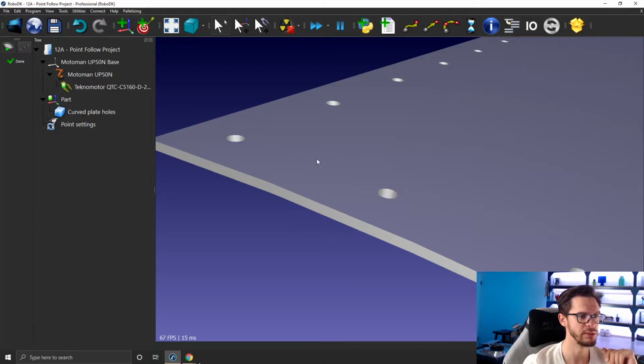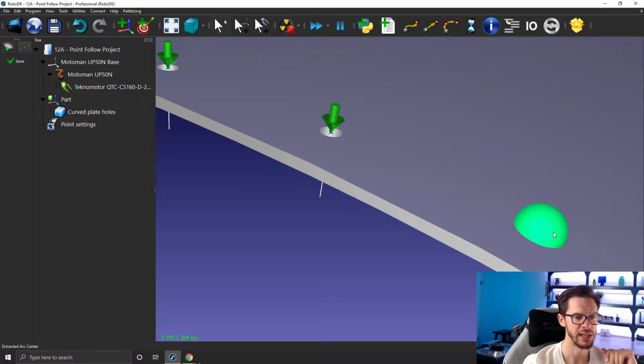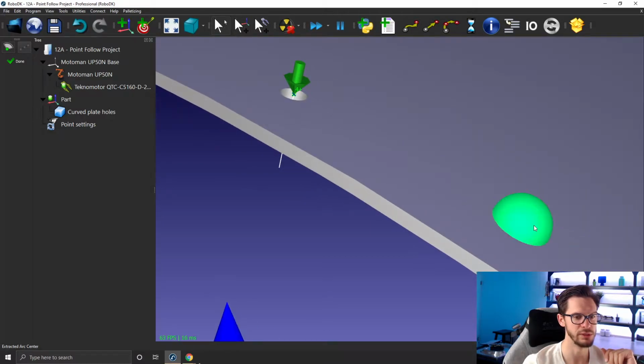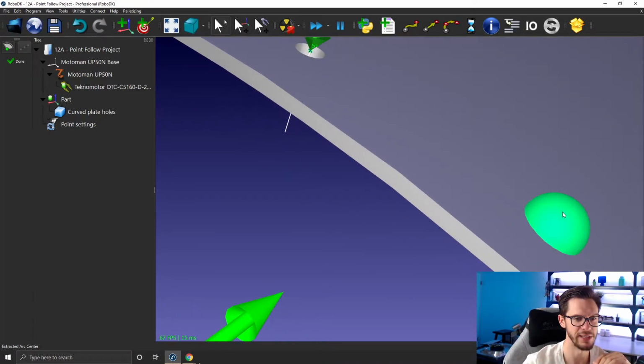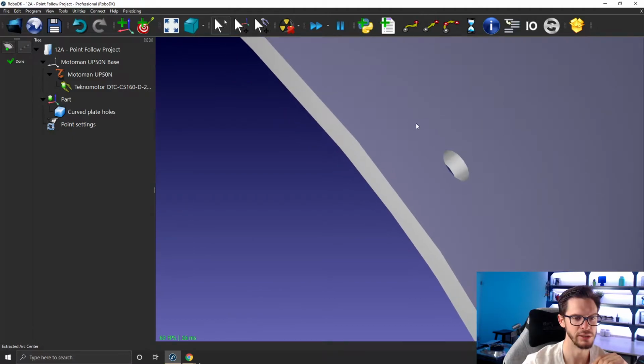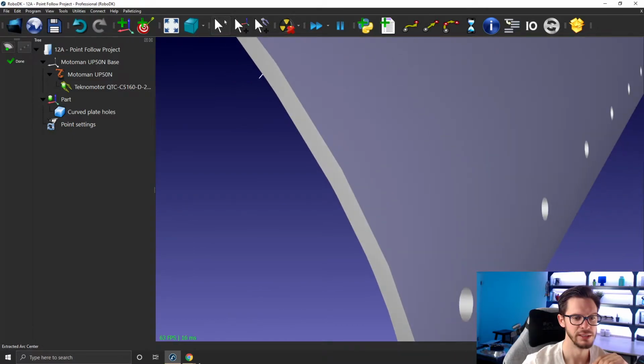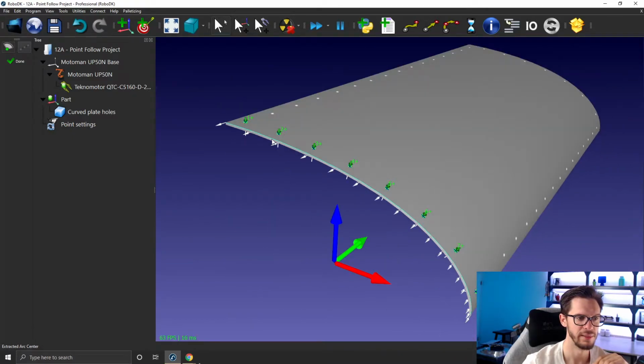But you will see here, if you bring your mouse near one of the arcs here, it will create a bubble, and if you select it, it will create a point directly in the middle and normal to that surface. So it will take the arc center and make sure that it's really the axis of that arc here. So I can go ahead and select that section here.